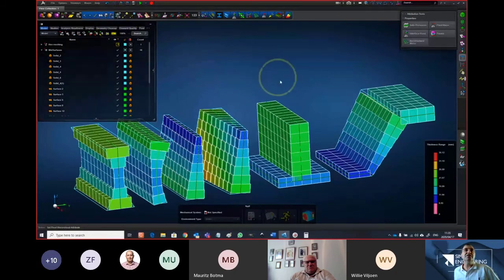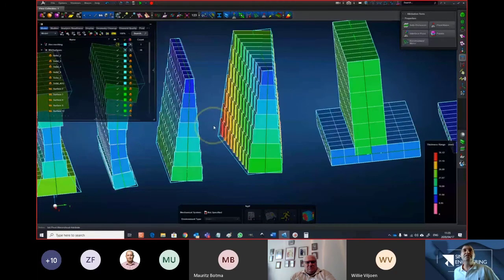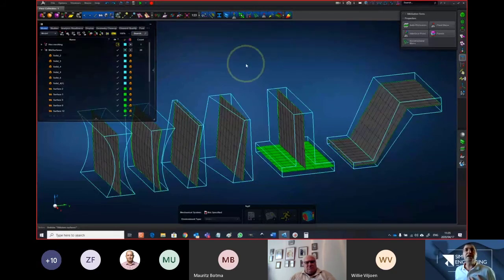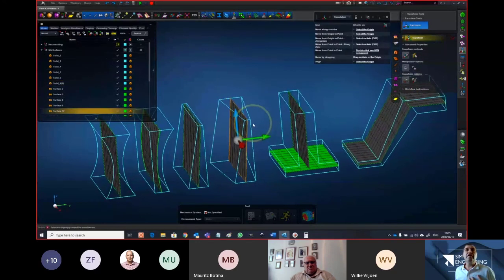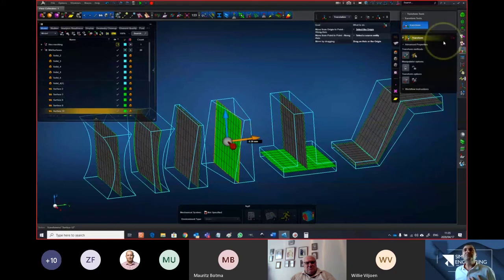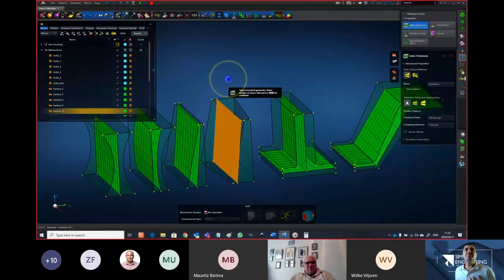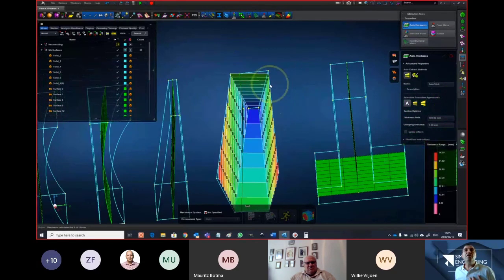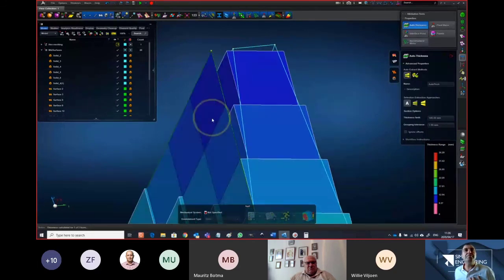So if I just switch the wireframe for the solids on, you can actually see how each and every element represents a different thickness. And just to show that those mid surfaces didn't need to come from the actual solids, you can actually move a surface into a different position, and Apex will still attribute the offset property correctly. So I'm just going to do this now for this guy. And as you can see, even the offset, even though I've actually exited the solid in this case, I didn't mean to do that, but it worked well.